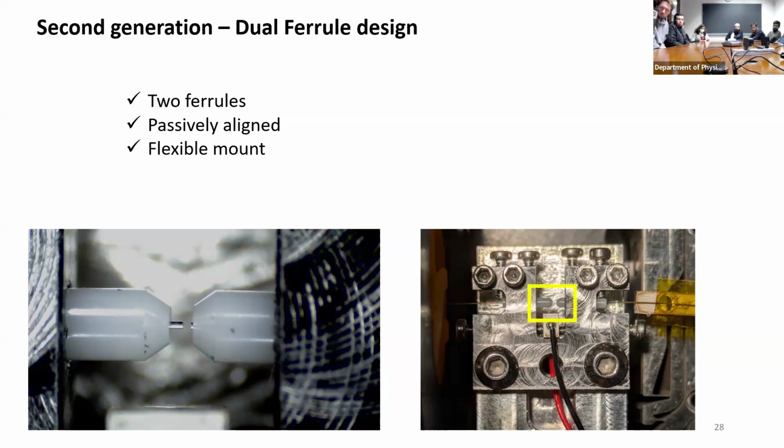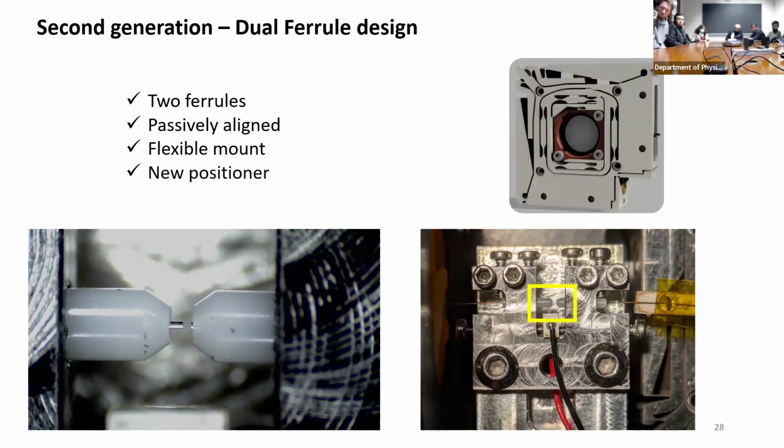And the third thing would be to use a better positioner. So this is, I mean, it's a complicated image, but this is a Colibri manufactured flexure-based positioner that can use a piezo to amplify the movement so that you can move up to 400 micrometers with just a piezo. You can use lever systems to amplify it. So maybe you can remove the handheld part of the system altogether. So this is what we tried, the two designs that I showed, this one and the other one, and I'll show you the results from it.